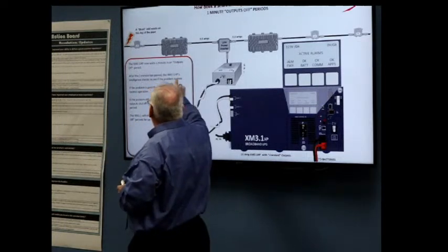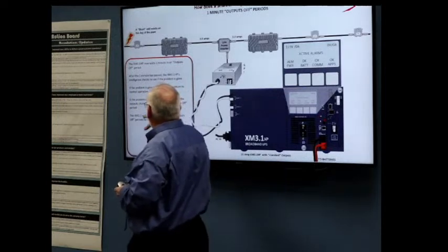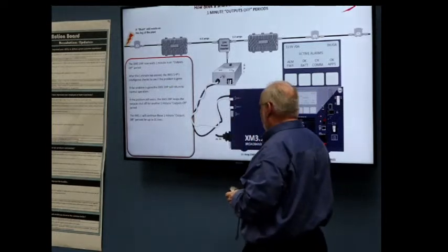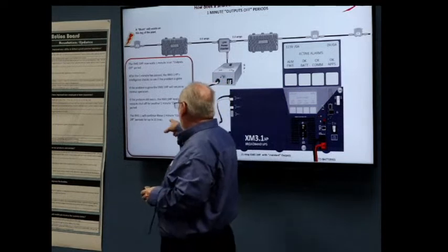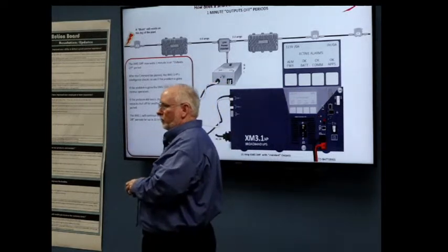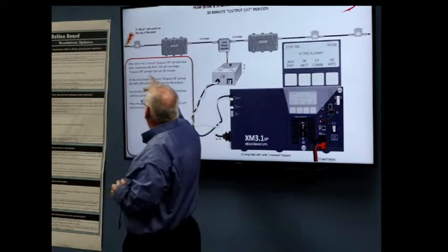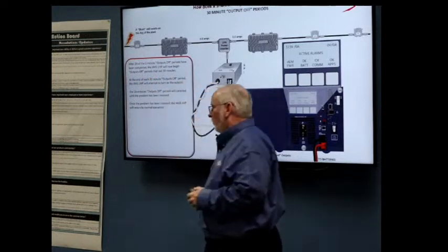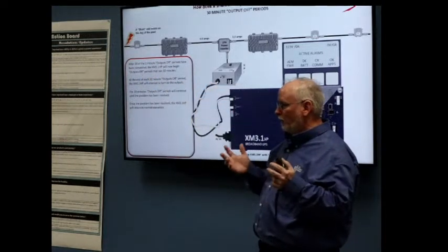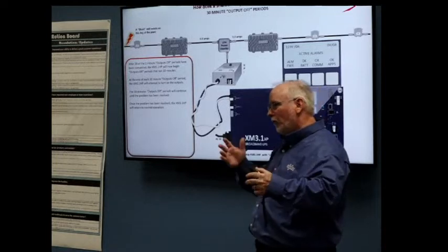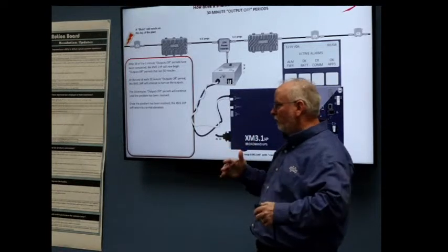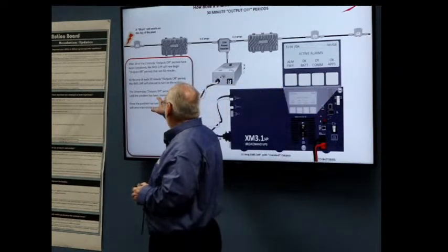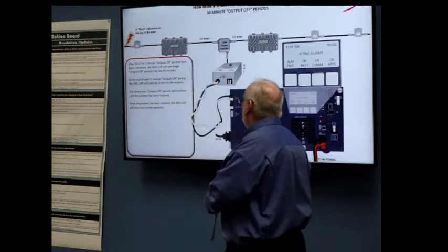After a minute has passed, it will do an intelligent probe. So what it's going to do, it will try it again, right? It'll turn it on, ping it, still sees a problem, shuts itself off. It'll continue these 1 minute output off periods for 20 times. Then, after 20 minutes, it will begin to turn off for 30 minutes. So for the first 30 seconds, it's on trying to run, then it goes into this pulse once a minute, just testing things. And then after 20 minutes, it's once every 30 minutes. The 30 minute output off periods will continue until the problem's resolved, so it just keeps on chugging.